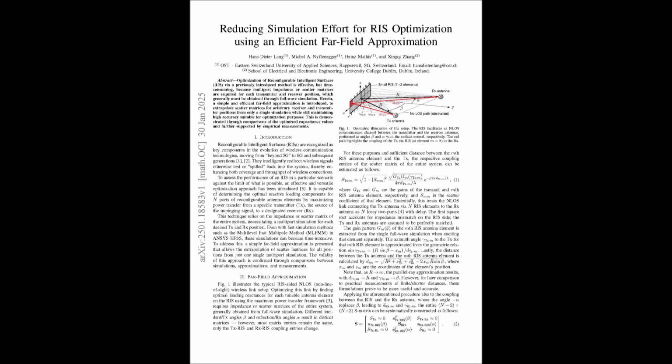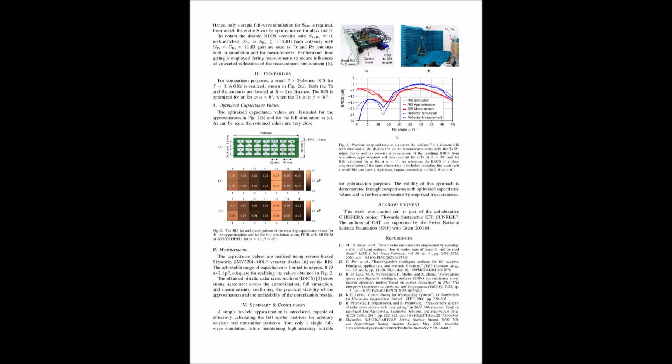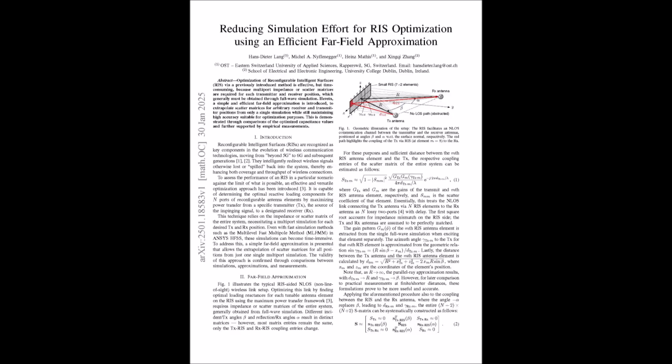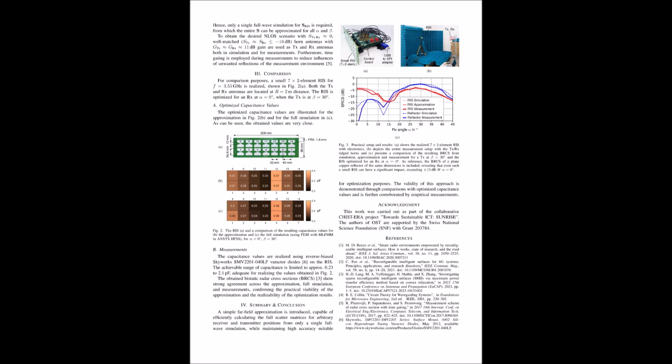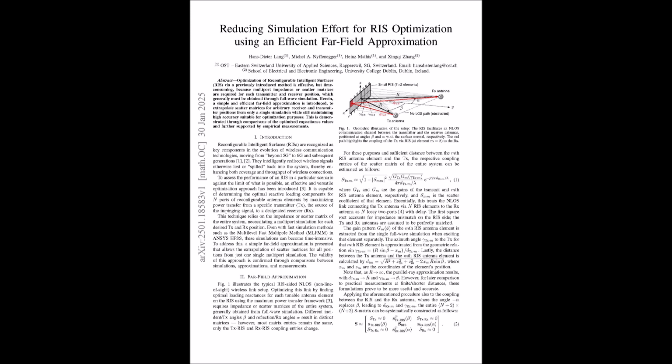You got it. Now, the next part of the equation might look familiar from physics class. It's the term λ/(4πd_TXm). This is essentially dealing with how the signal strength decreases as it travels over a distance. Ah yes, the inverse square law. The farther the signal has to travel, the weaker it gets. In this case, d_TXm represents the distance between the transmitter and the specific RIS element. And λ is the wavelength of the signal. You're absolutely right.